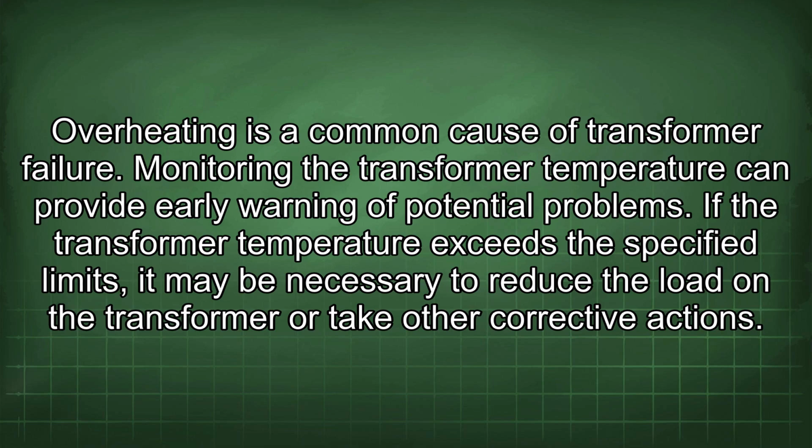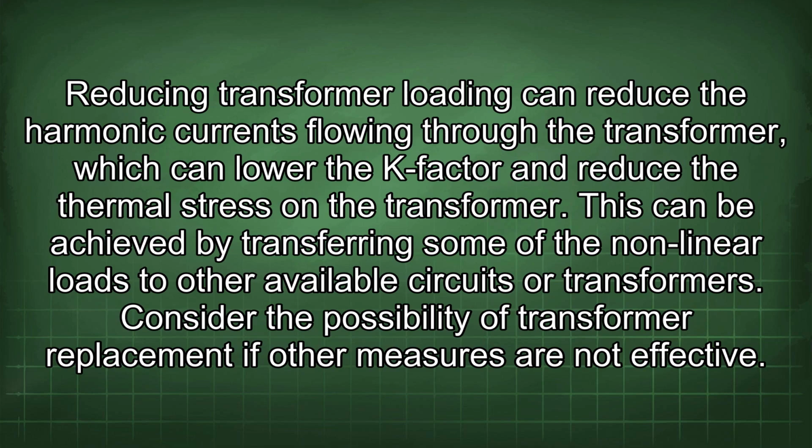Reducing transformer loading can reduce the harmonic currents flowing through the transformer, which can lower the K-factor and reduce the thermal stress in the transformer. This can be achieved by transferring some of the nonlinear loads to other available circuits or transformers.